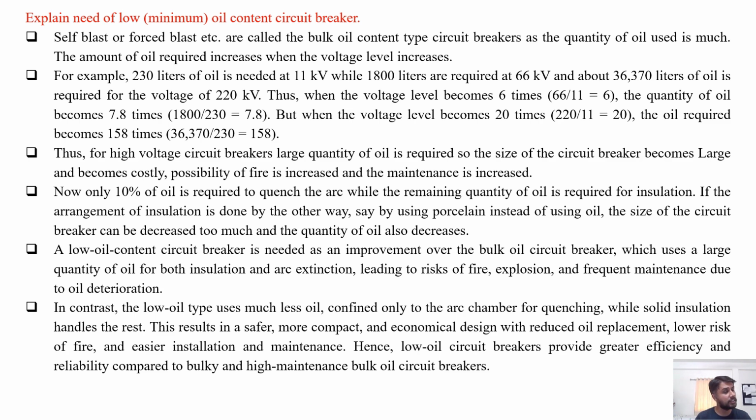Possibility of fire is increased and the maintenance is also increased. Now, only 10% of this oil is required to quench the arc, while the remaining quantity of oil is required for insulation purposes. Now, if the insulation is arranged in another way, that is using solid insulation, that is porcelain or bakelite material or epoxy resin instead of using oil.